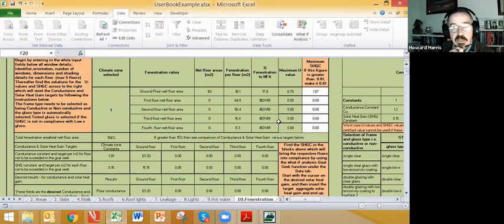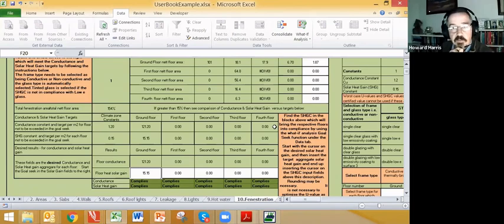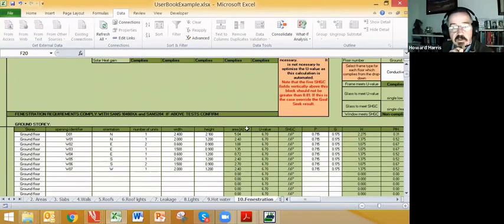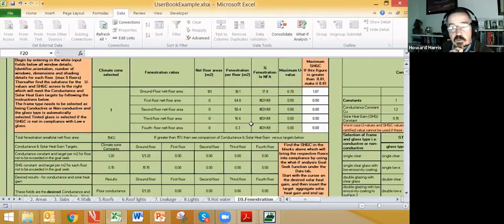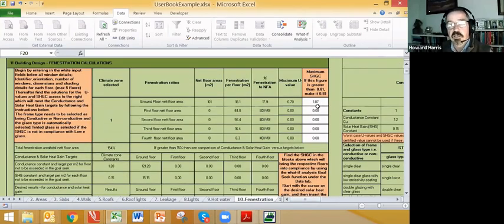and you can see by changing your inputs how the requisite U value and SHGC can be generated, and then one can go to market and ask for a mix of windows which will on average meet the minimum or not less than the minimum U value requirement of 6.7 or the 0.81 it would be, which would be a worst case for a single clear glass solution.